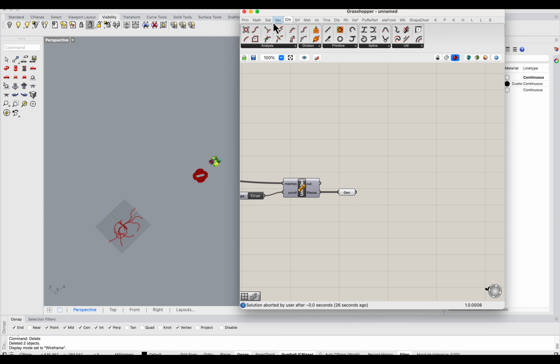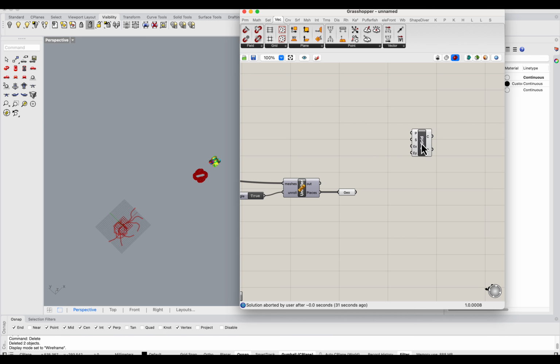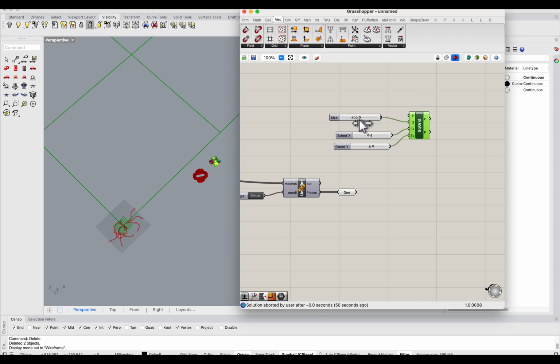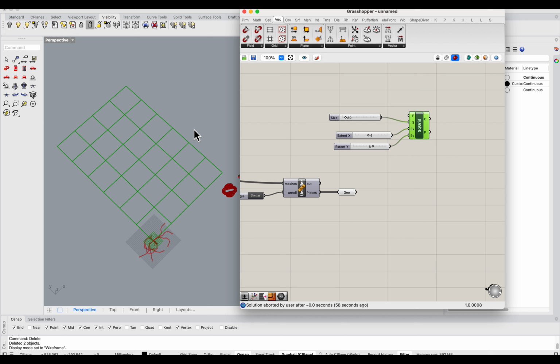So let's find out where the grid is. So I'm going to go to this vector grid, and I want to create a square grid, and base plane is X, number of cells in X and Y, well, it's 5 by 5. So what we could do is like maybe create a grid of 4 by 6. And I can do a grid size of, let's say, 500. Well, that's too big. So let's shrink it a bit. So what I want to do is place each of these elements inside of these grid cells so that we can process them individually. Okay, so I'm going to do 60.